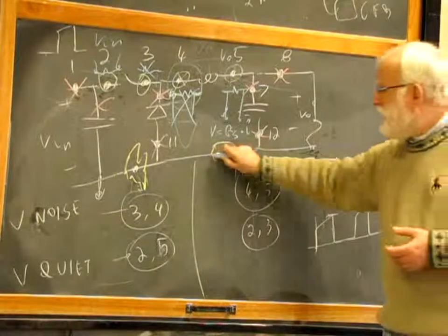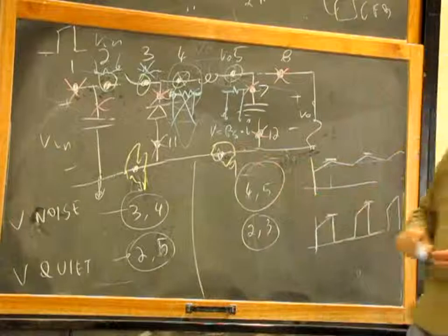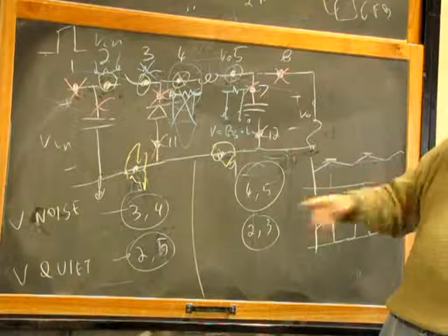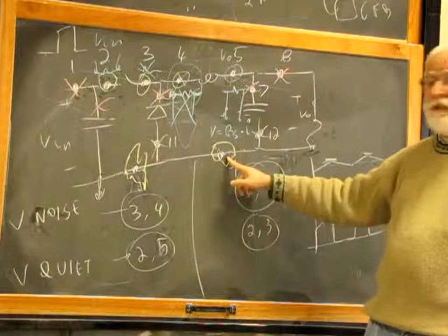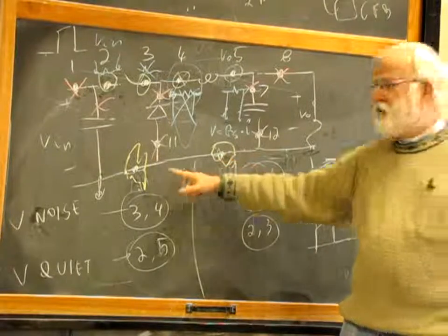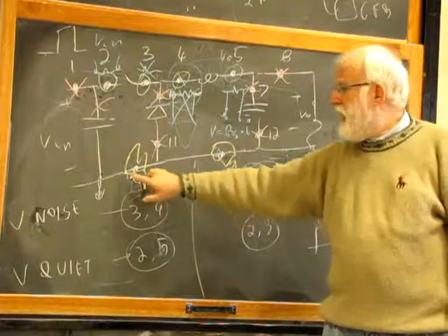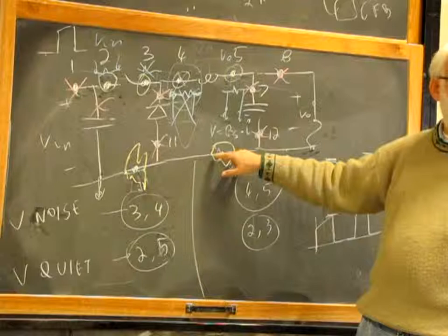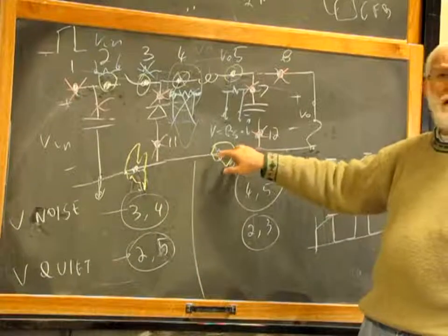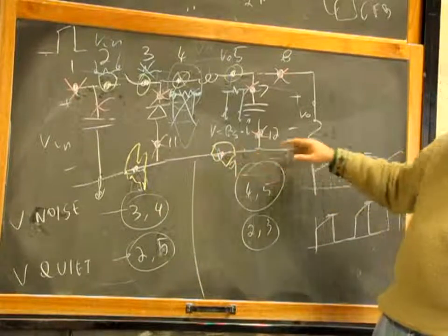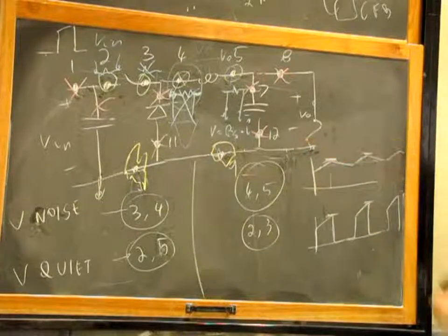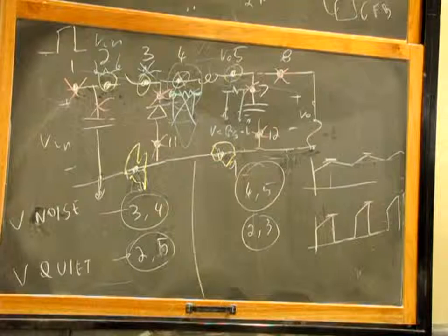What if you put your sensing resistor over here in 9 or 10? Well, you have the same problem of power dissipation. In 9 you have more power dissipation, in 10 you have less, and both of them have a common mode voltage across them that is 0. So you don't have any common mode problem, but you're just messing up the reference voltage of your load, which is not exactly the same as the reference voltage of the input.